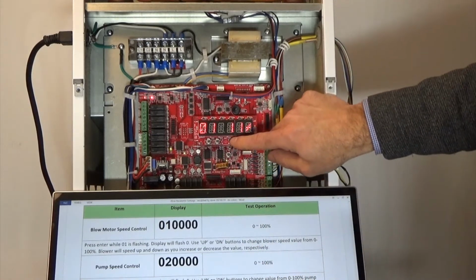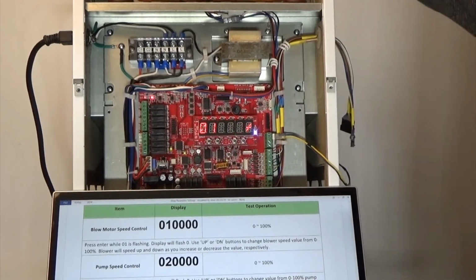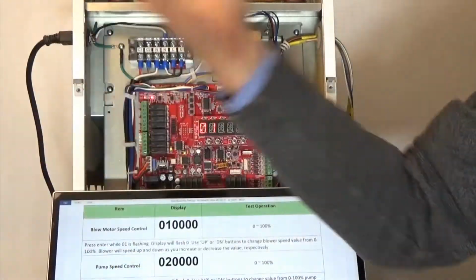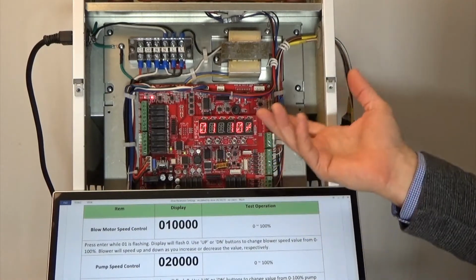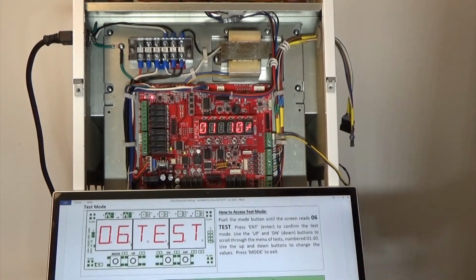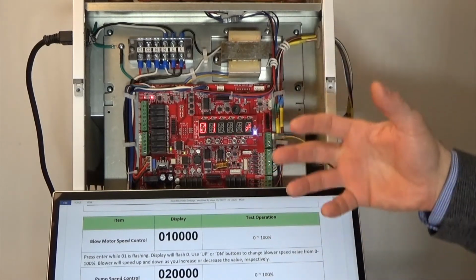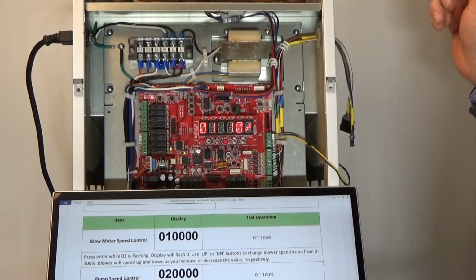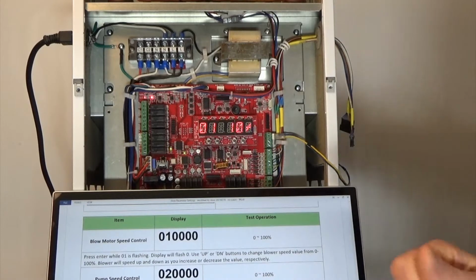And then on the other side, we can run it down as low as we want to see what minimum airflow rate we need to be able to move air through the house, through the ductwork, and then that would be our minimum setting. So we can use the blower, the parameter 1 in test mode, to test the maximum and minimum blower speeds that we can then use to set up our controller parameters in mode 3, 4, and 5. So our general heating and cooling parameters.